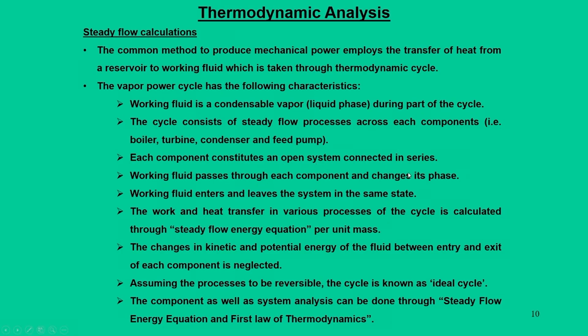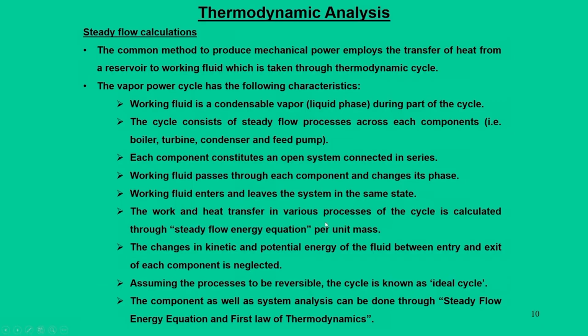We will see how they are connected. The working fluid passes through each component and changes its phase. The working fluid enters and leaves the system in the same state. That means it enters in liquid state and also leaves the system in the liquid state. We will see how it happens. The work and heat transfer in various processes of the cycle are calculated through the steady flow energy equation, based on unit mass. The changes in the kinetic and potential energy of the fluid at the entry and exit of each component are neglected, and all the processes are assumed to be reversible.